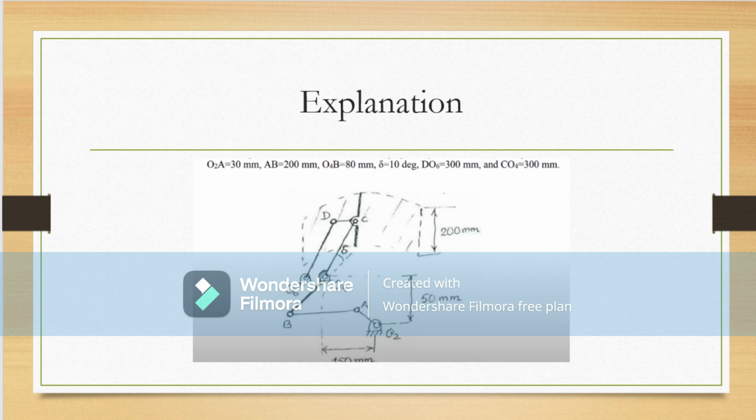Now with those in mind, we vary the coordinates per position of the crank. As the position of the crank varies, all the other factors that depend on it also vary, and this brings about the displacement analysis. So the displacement can be found by finding the location of the coupler for every position of the crank using these geometrical conditions. So what we do in MATLAB is that basically we provide the condition of the links, like the length of the links and the geometrical constraints which basically position the link with respect to its environment, and then based on that we rotate the crank.